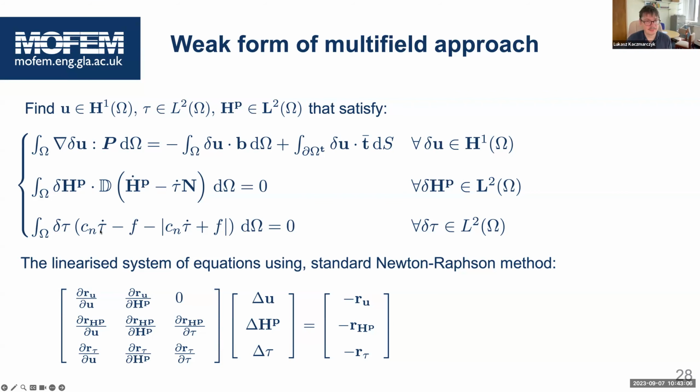And then we write our conservation of linear momentum in the weak sense. Then we put the formula for the flow rule, and then we deploy on it the Galerkin method, as you can see. So that equation has to disappear for any variation of the Henky stress. And then we have a consistency equation when we test it by tau, which is our plastic Lagrange multiplier.